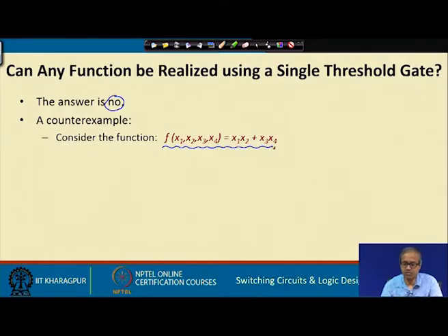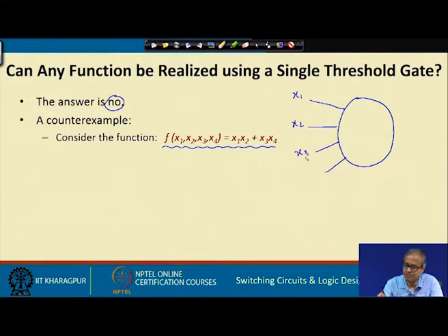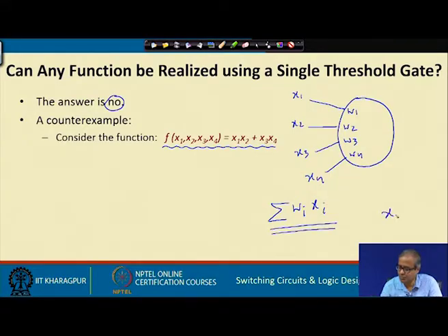One thing we would like to tell you is to understand how a threshold gate works once more. The inputs are x 1, x 2, x 3 and x 4 with the weights W 1, W 2, W 3 and W 4. Now, when you calculate the weighted sum, if some particular input, let us say x 1, is 0, then that component x 1 W 1 will not appear in the weighted sum; it will become 0.